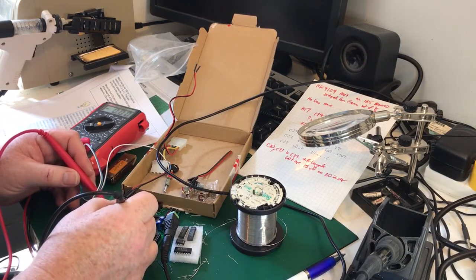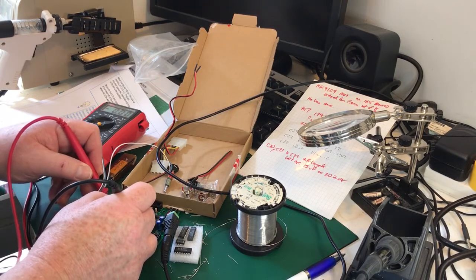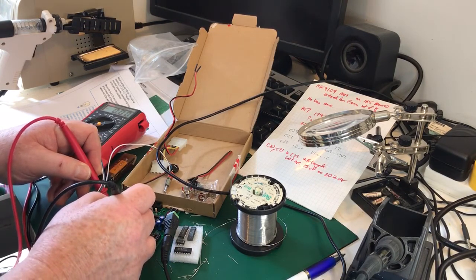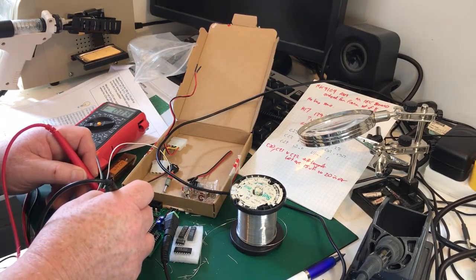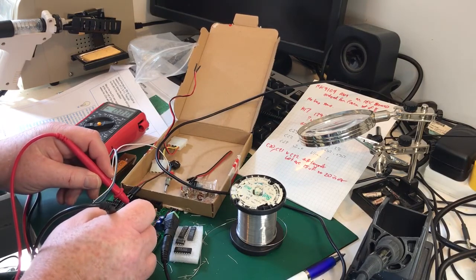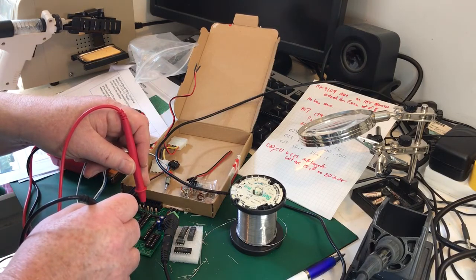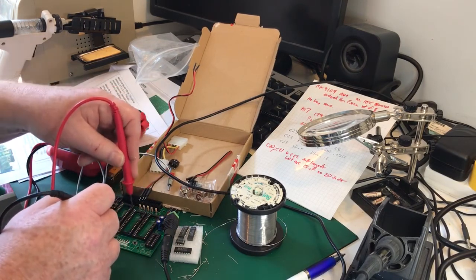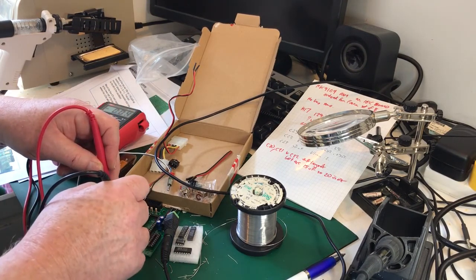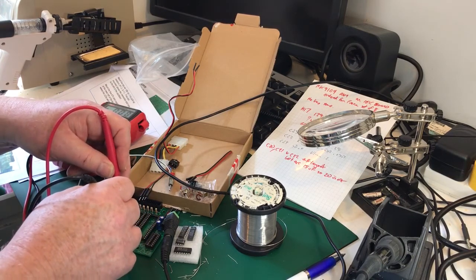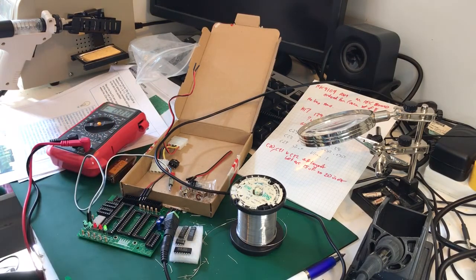So I think just check it's on the PIC as well. Yeah, the PIC's got some unusual places it gets its voltage, isn't it? Across the middle there somewhere. Maybe. Can't remember now. Really ought to check. But I think the EEPROMs are similar, got a ground and a 5 volt rail in the same place, yep. But the PIC isn't, I don't think. So I better just check it's the same pin out for now. I'm sure it's across the centre of the chip somewhere. I better get a PIC pin out and check it, hadn't I?